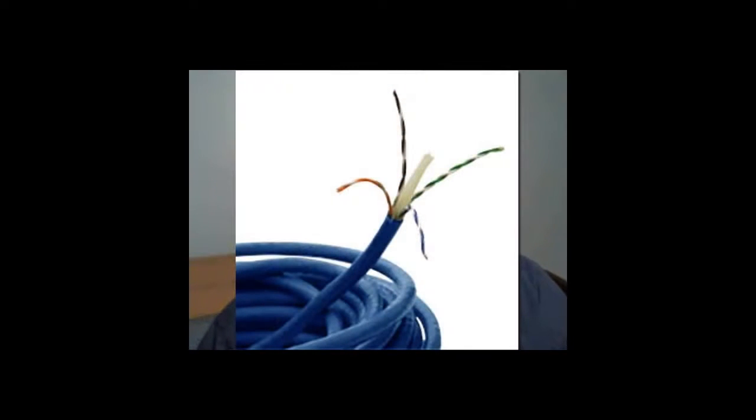Have you ever seen one of those plastic coffee stirrers when you get coffee and donuts? If you look at it from the end, that's actually looking down the stirrer, it's in the shape of an X with 4 channels in it. And to get gigabit speeds in Category 6 cable, they developed a 4-pair cable that has something like this long coffee stirrer sitting in the center of the cable, which physically separates each pair from one another. The central plastic core winds its way through the cable, and it kind of corkscrews or spirals the pair while it separates them. The combination of the physical insulation between pairs from this plastic piece, as well as the intense twisting, keeps the data moving along, and this is called Cat6 cable.